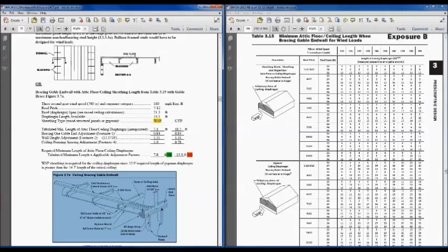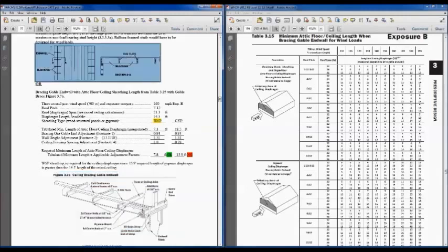If you're not balloon framing, if you're only framing up to that vaulted ceiling and then using shorter studs above that, you're going to need to make sure you block or use this detailing for that ceiling diaphragm as well. So those are a couple things that you need to be aware of just to take care of some of the load path. So if you balloon frame, again, you can block into the rafter system.